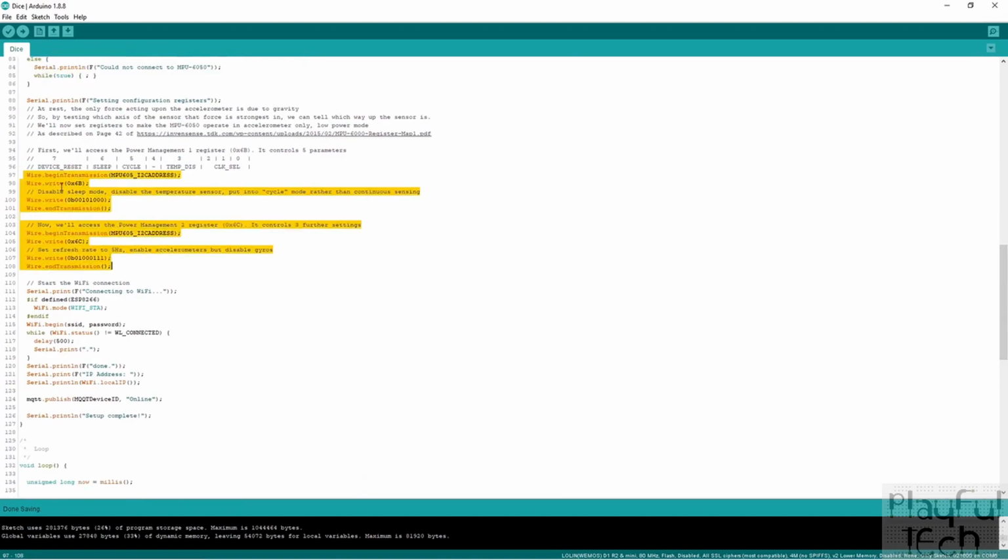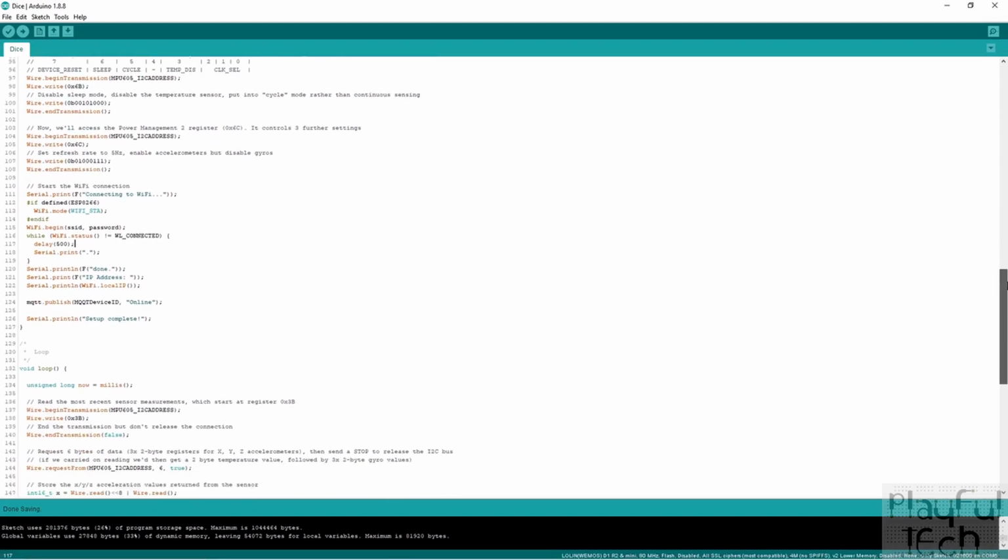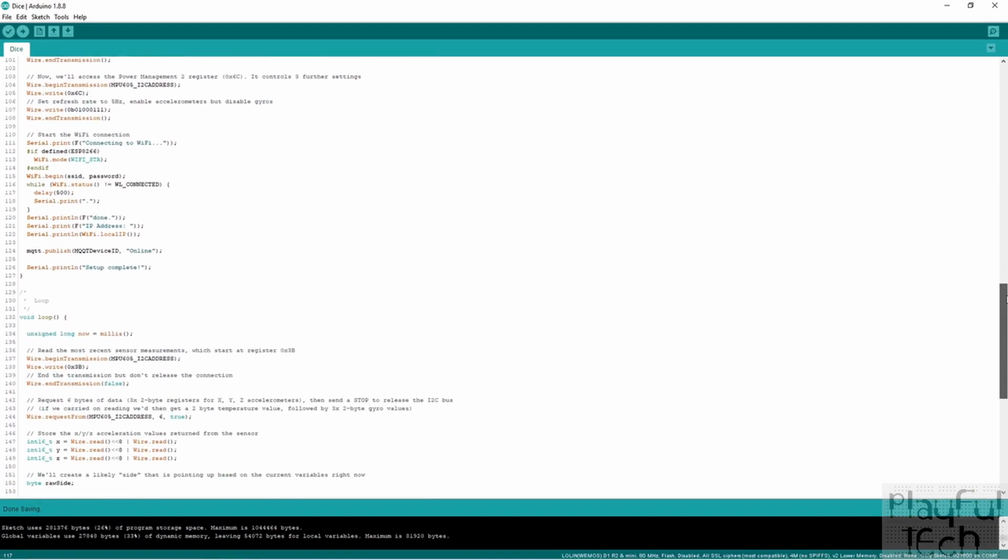Same idea again, you first specify the address you want to write to, and then you write the new value using write this time. So it's really powerful, and you can use this for any I2C sensor at all. If you've got the datasheet to refer to, you can write your own functions to read and write any values you want to the sensor. It's very powerful. Okay, phew.